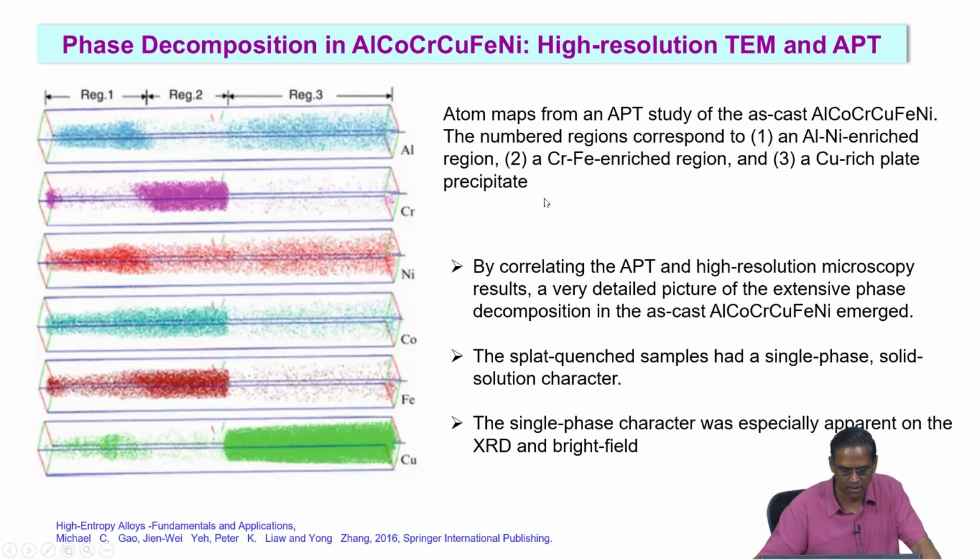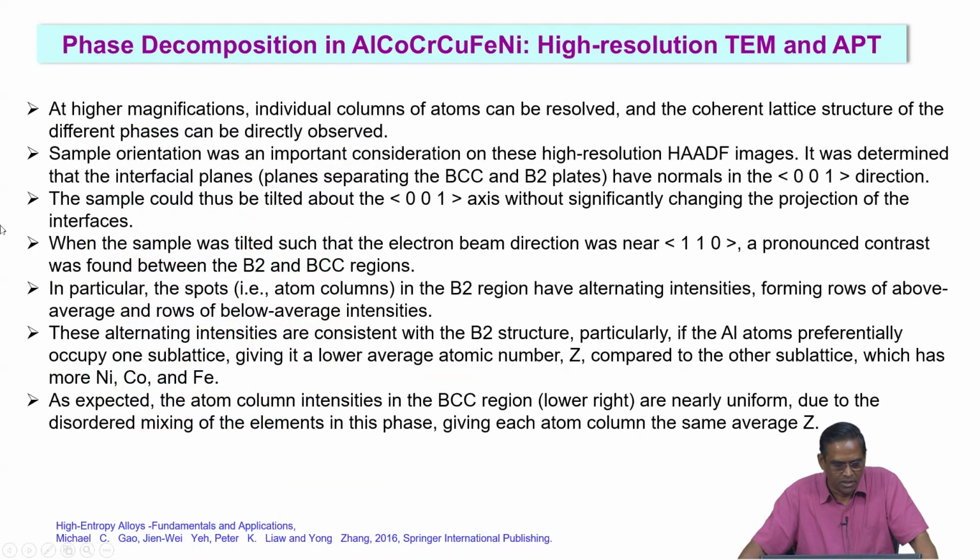So, this is another characterization method. Suppose you want to look at the decomposition at atomic scale, and the moment you identify phases having 2-3 crystal systems mixed, then it is better to select these kinds of microstructure characterization techniques to get the full idea about the phase composition. So, this has just summarized what we have seen in the previous slide,